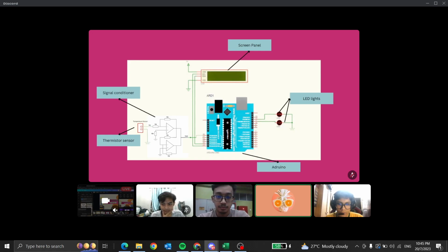Next, once it has measured the temperature, it can convert this measurement into a physical quantity such as voltage and also current. Since our project focuses on reading voltage values, we will base our calculation on finding the voltage. The sensor has two terminals, and since it is a passive component, it doesn't matter which terminal is connected to ground and which one is connected to the signal conditioner.